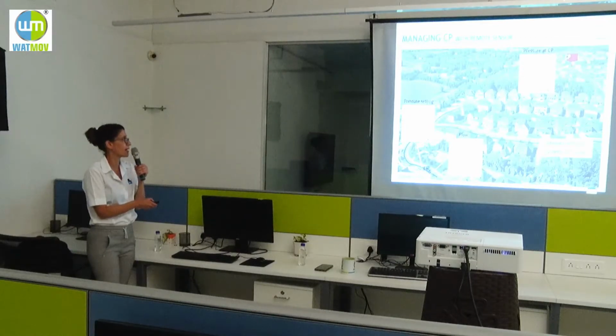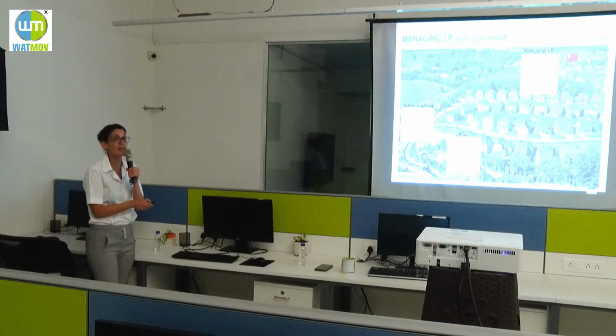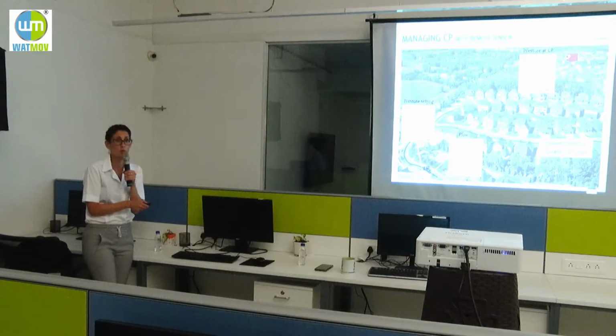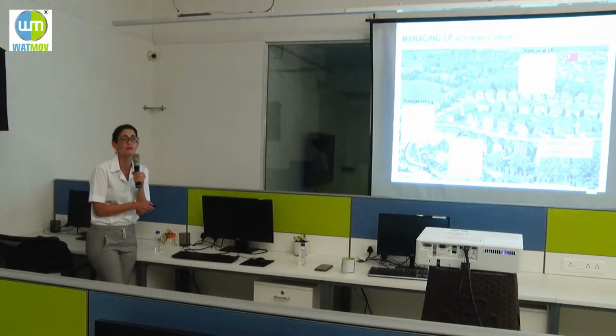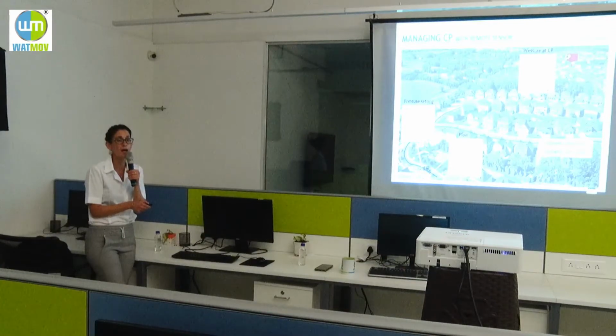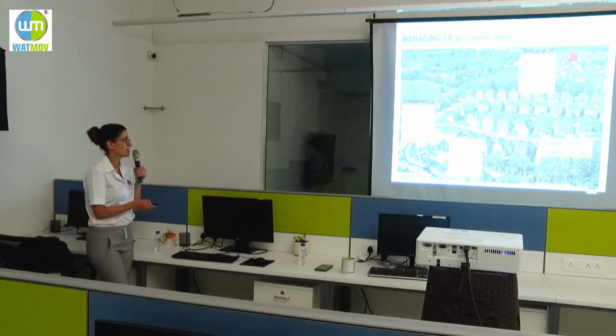Because in the previous solution, when we talk about the nights, the pressure is high at the critical point when the demand is low. It's 45 meters, they don't need it. The minimum required is 2 bar. So here, we are taking care in a very sophisticated way. It's more complex and more sophisticated to understand, but we are taking care all the time to apply the 2 bar at the critical point and reduce the leakages.